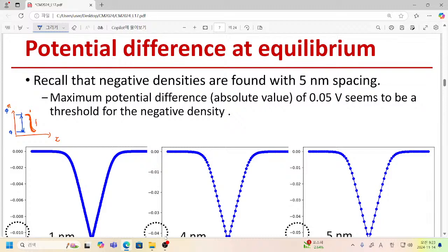So now depletion region is significantly reduced. For example, it has some square root behavior. If you increase 100 times in your doping density, then it will shrink 10 times shorter depletion width, however, increase of your potential is not that high because it takes a logarithmic scale.